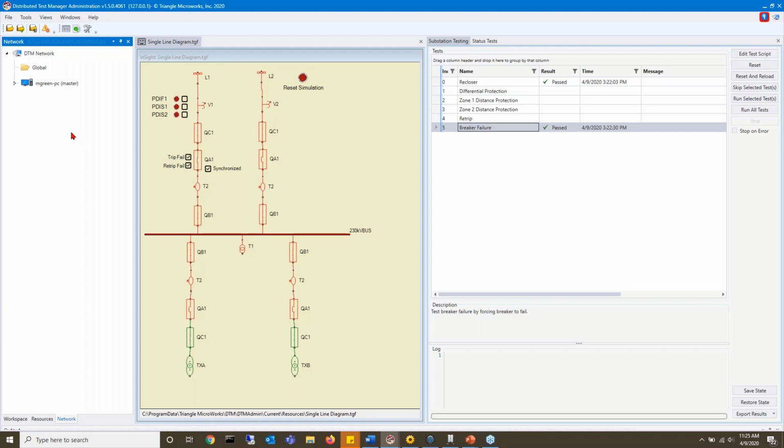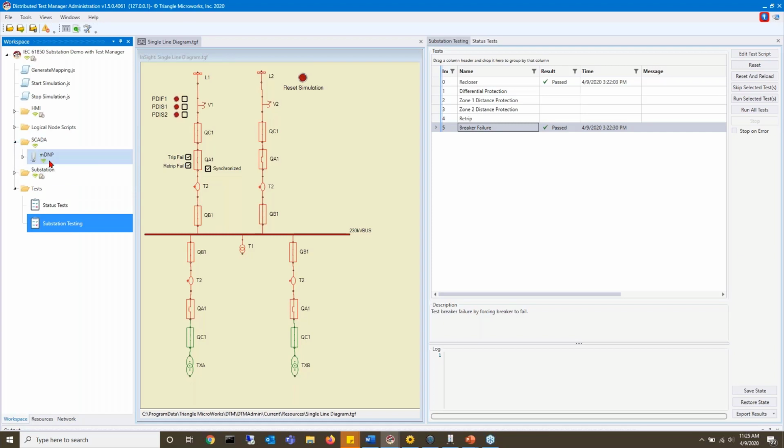Yes, absolutely. So if you are testing your SCADA system, you can mix and match all these protocols beneath it. So right in this example, we have an upstream, say, DNP device. That's what our SCADA is, and that's going through a data concentrator. But of course, in your substation or multiple substations, you could have a variety of different protocols.